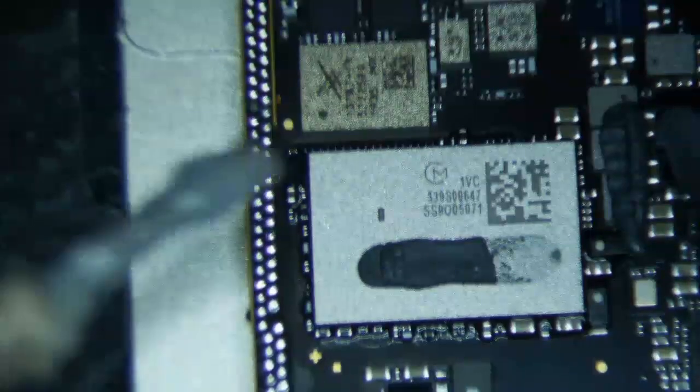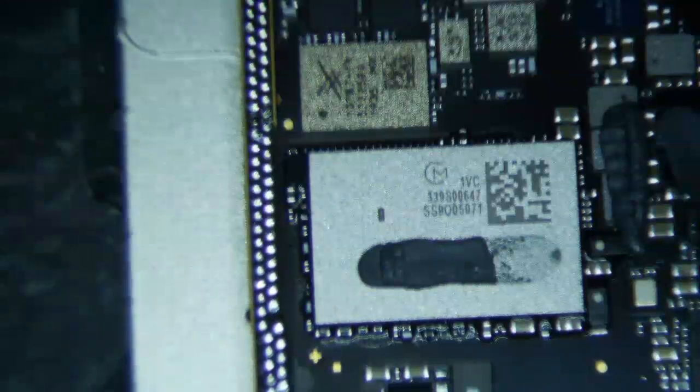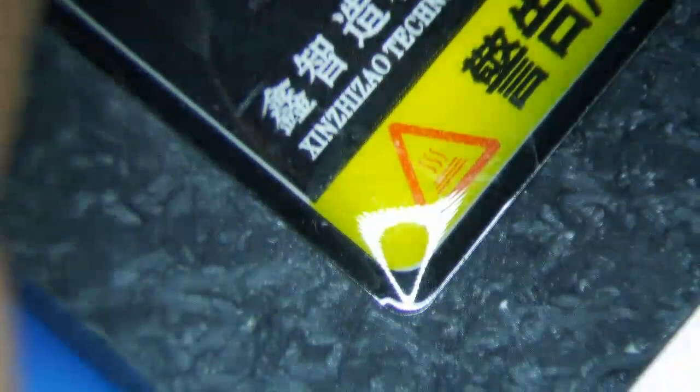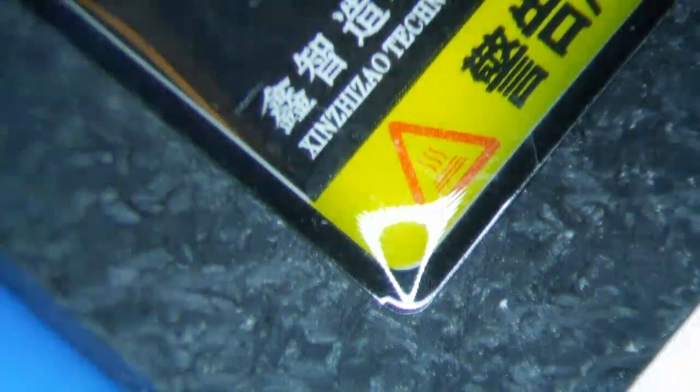I think so. If you're careful removing the board, then you're not gonna have as much work to do. But if you're not gentle with it, or you decide that you wanna take off all the solder and re-ball it, then you're just gonna have way more work than you want. So what I'm doing now is I'm just putting a little bit of flux all around it, okay? Because the flux is gonna be mandatory to get this thing back on. So I'm just going around it with a big ball of flux and just touching it up.